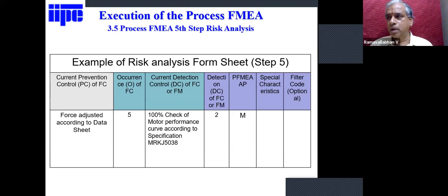That's what they give. Then special characteristics. For example, in every product there should be some special characteristics. Once again, I take the pen example. You have the pen, there is a barrel and you have a cap. The pen's barrel OD is a significant characteristic. The cap ID is a significant characteristic, right? Then only it will have a proper press fit. So wherever the interface is taking place, that will be the significant special characteristic which we need to derive or get from the customer.